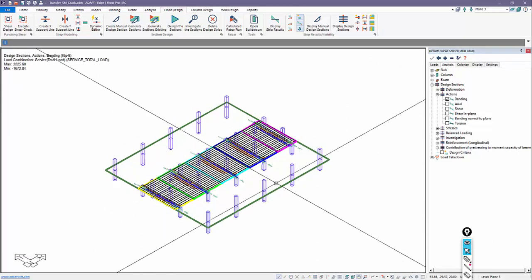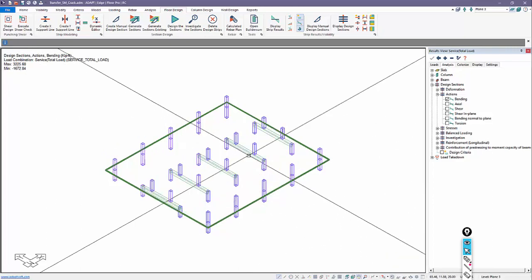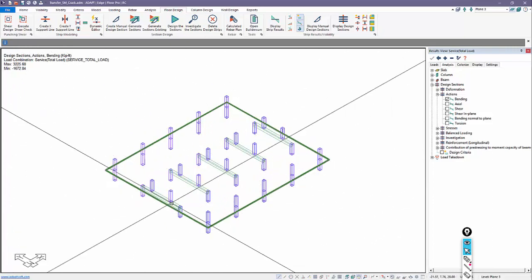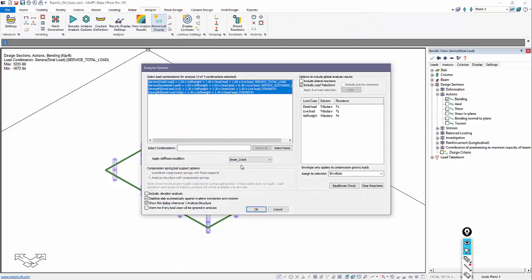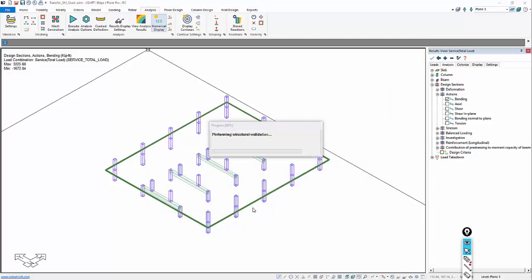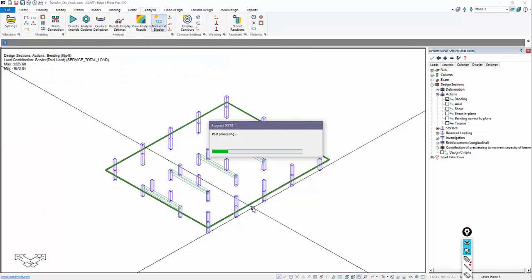The other option from the global solution is to rerun this. I can now rerun single level under analysis with beam crack, but rather than using the tributary, I'm going to use the uncracked solution from global. Remember, I ran global analysis with the uncracked usage. I'm rerunning the single level as if the beams are cracked, but I'm using the global reaction versus the tributary reaction. Okay, and we'll rerun this. And this is our third workflow for obtaining a beam design with use of modifiers.